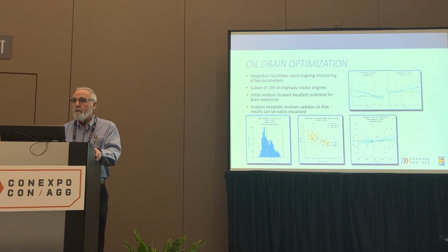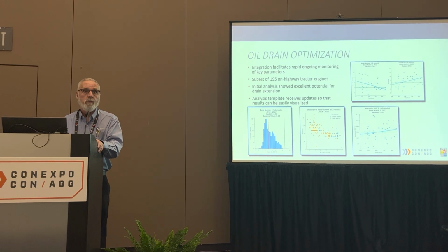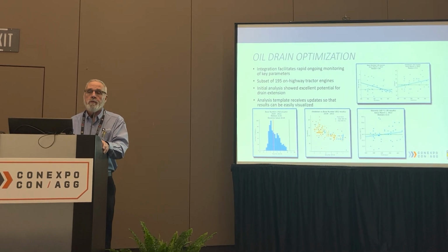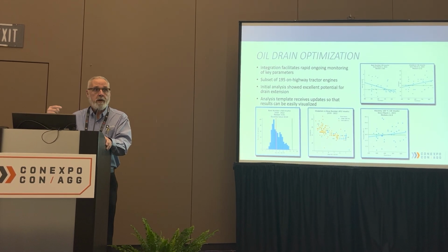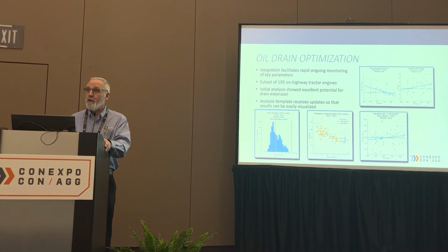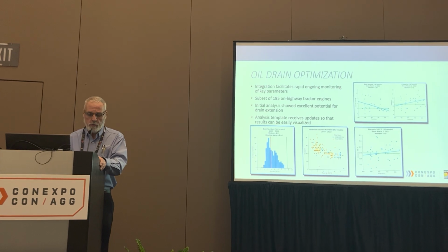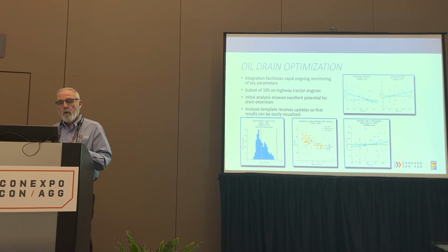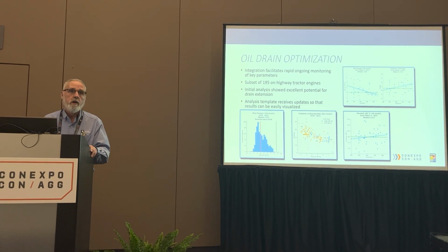interval. Too many people say, yeah, we want to extend our drain interval. And they say, all right, we're just going to push it from 250 to 500. And they don't do oil analysis when they jump that, because typically they're pulling oil analysis at the drain interval, and so they're just not taking advantage of all the capabilities that are there. Doing this makes it really quick and easy to determine what that drain interval should be.